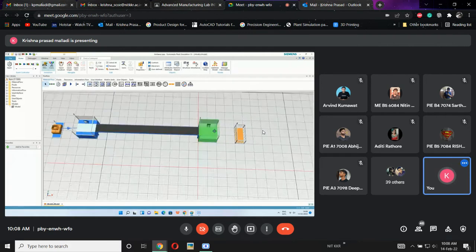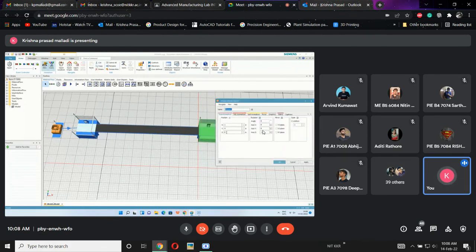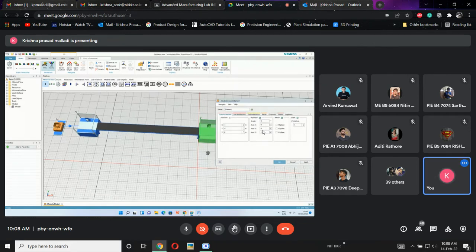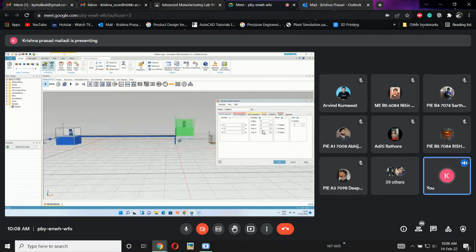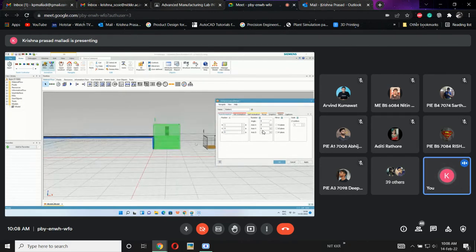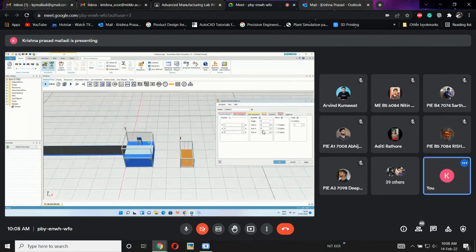Okay, this is my machine and I want to increase the height. For that, either I need to go to 3D properties. Here I can transform the height. It is a position change. If I click this one, now what has happened? The transformation is changing. That is not the correct method. To increase this height, in this method you need to enter into scale. You need to disable this one, and there will be X, Y, and Z. You can directly change it here if you want.